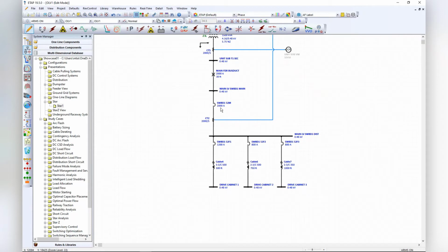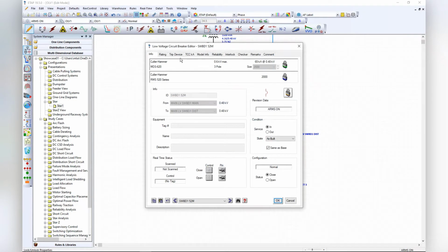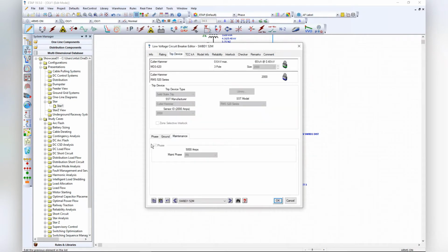And what you do is you just go and flip that selector switch, and that brings the maintenance switch in place. And the maintenance switch, people have all sorts of fancy descriptions for it, but it's just an instantaneous override. You're gonna see it now on the TCC coordination, and that instantaneous override, instead of just being a normal instantaneous, I don't know exactly how they make these things, to be honest with you, but it's got a much shorter time band.